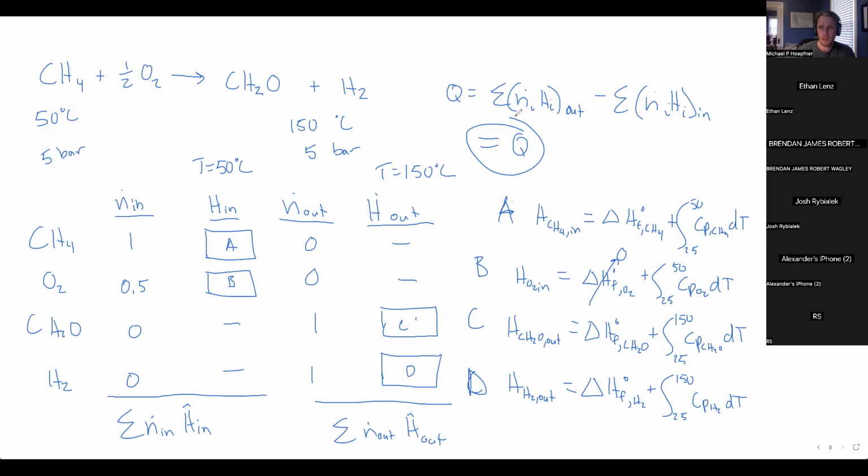So with this, I wouldn't have to have made this a complete reaction, right? I could have said it only goes 20% to completion. I could say it goes 60% to completion. And that would update my material balance, but it would not affect any of my enthalpy calculations. So the further this reaction goes to completion, the more my Q is going to change. But if I react less and less, I don't have to update my energy balance at all. I don't have to update my enthalpy values at all. Any change in how much the reaction progresses is lumped directly into that material balance.